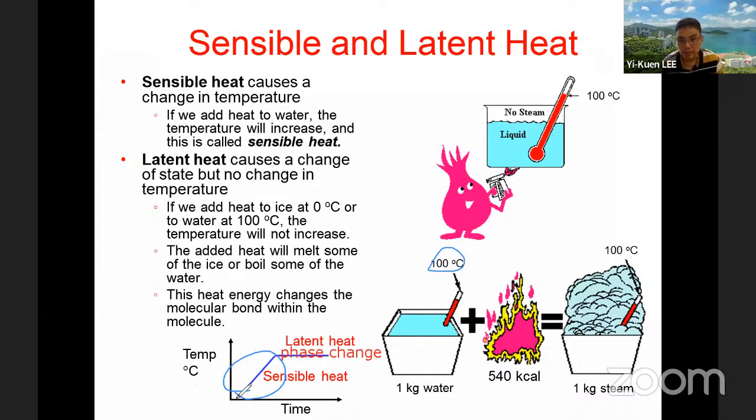Of course, for this part we call it the sensible heat, and for this one, latent heat. Again, the amount of energy you can carry with latent heat is much bigger than this one. That's why when we design this air conditioning system, or HVAC in general, we prefer to have phase change. That is an important thing I want you to understand. Do you understand? This is important.